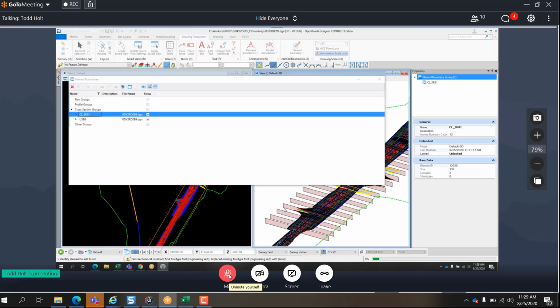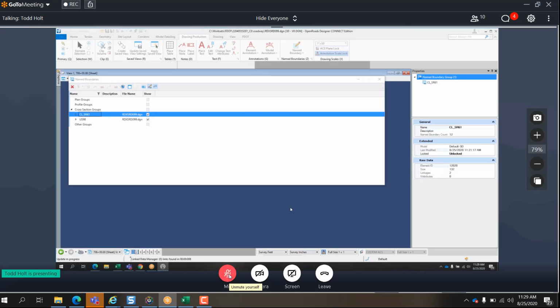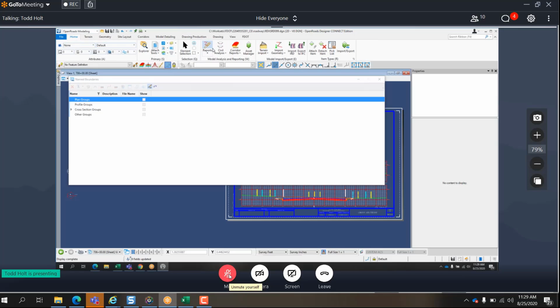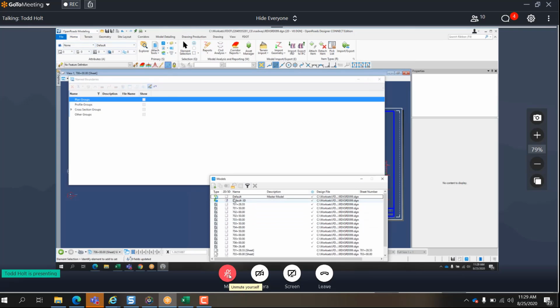So this is going to create cross sections for centerline State Road 61. I'll do the same process for the US 98. After, when I come back into this to show you guys. So it's going to cut the cross sections. I still need to get the table back on there. So let me cut the clips for US 98 real quick.